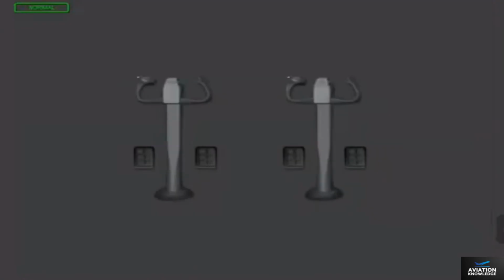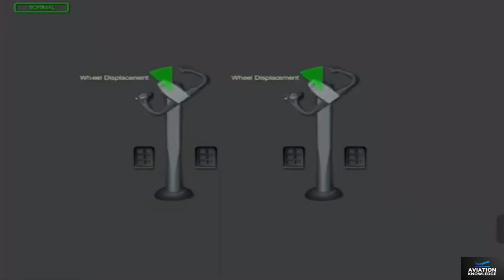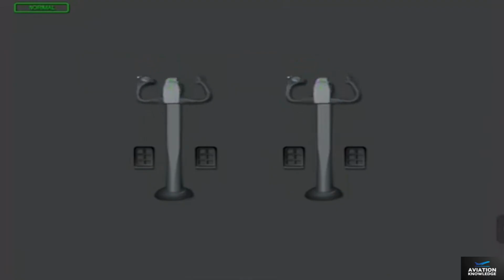In the normal mode, airplane roll control characteristics are similar to conventional airplanes. Unlike conventional airplanes, the control wheel does not directly position the lateral surfaces in flight. Instead, it commands a roll maneuver with the rate dependent on wheel displacement. Control wheel displacement incorporates artificial control wheel forces, which increase as control displacement increases. These forces do not change with airspeed changes.